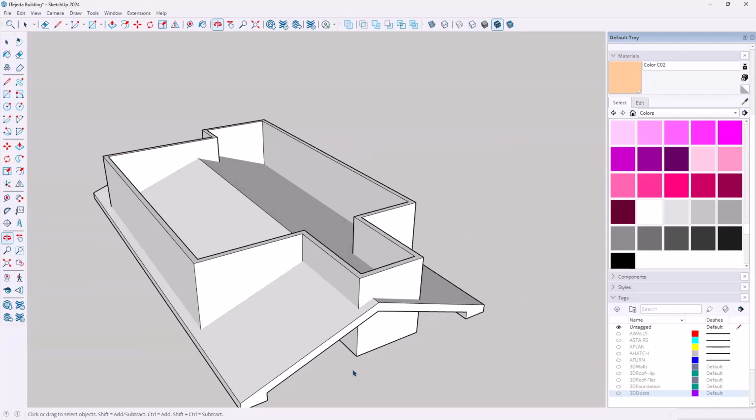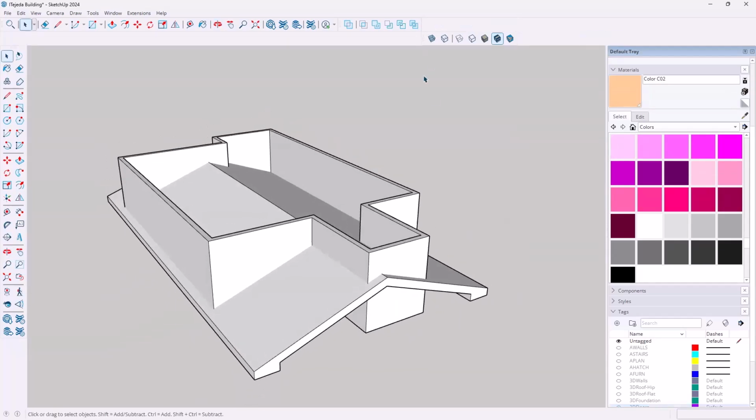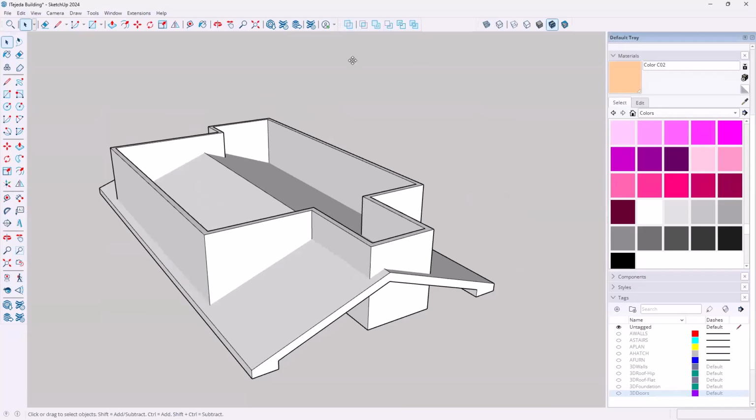And you can see that it's cutting right through, and that's exactly what I wanted it to do. Now, this is where I have to be really careful and patient with myself because I'm going to use a different solid editing tool. Sorry, that one is styles. Let me put that back up. I want the solid editing tools here. Okay, so the one I've been using so far is the subtract, but now I think I want to either use the trim or the split.